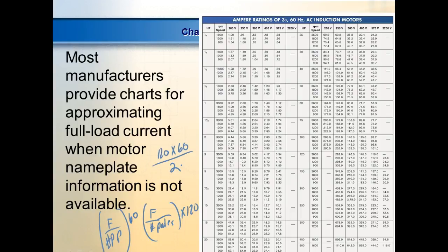So this is the start capacitor. The 2 brown wires are the start capacitor. The yellow is the common, and there's your 3 wires. And what are you doing here? You're changing the number of poles. So these have fixed speeds, right? This is a 3-speed motor.